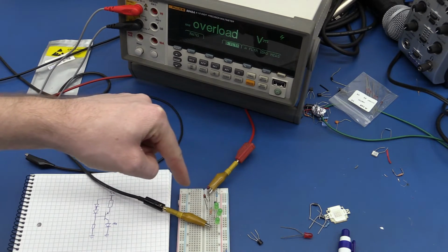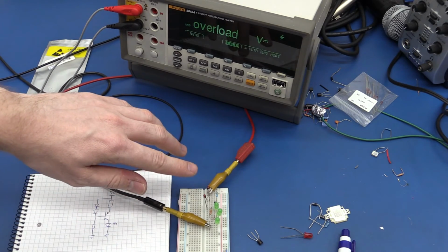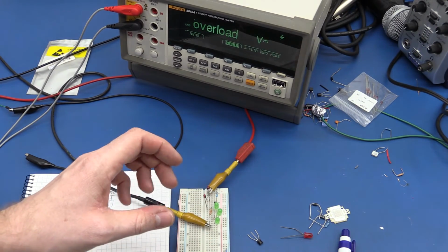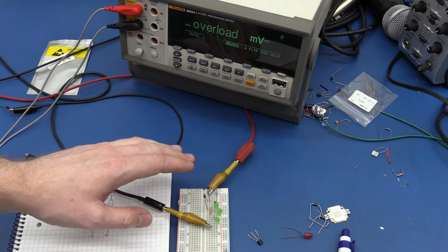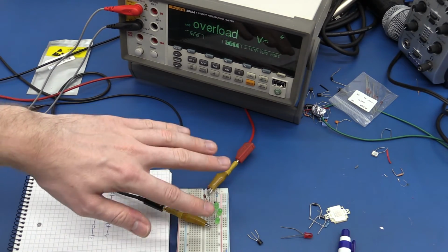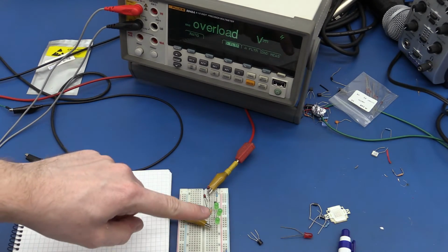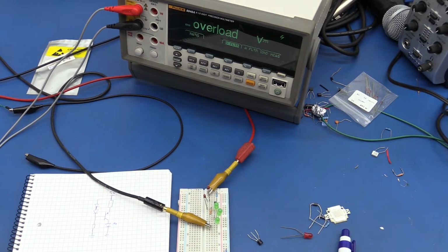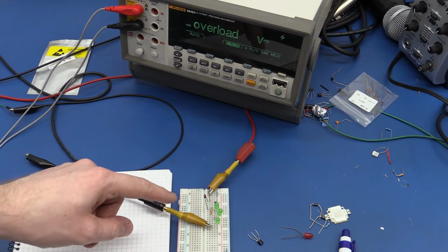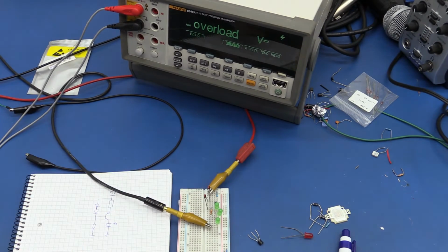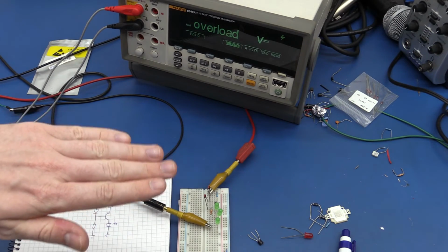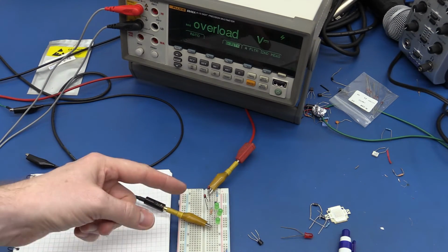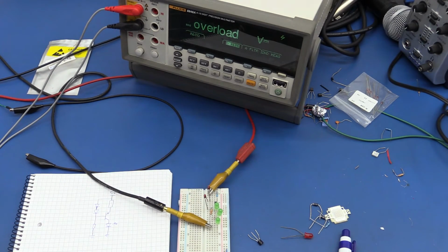So the dropout of the regulator remains constant, and you can then say that the more LEDs in series we add, the greater efficiency we get, as long as we keep the supply voltage just where it will regulate. So for one LED it's about 66% efficient, and for 3 LEDs it's much more, actually about 80 to 90%. But of course we wouldn't drive it right at the edge of dropping out of regulation, so we might add a bit and get 75% efficiency out of this.